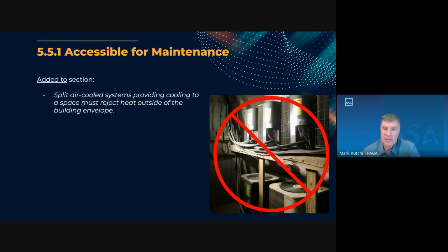I think the issue is that a lot of engineers make the mistake, as shown in the photo here, they just put these condensing units that cannot be ducted. They're not aware of other manufacturers who make ducted type units when they're faced with a situation where they can't locate the unit outdoors. So they use the right piece of equipment, it should be fine, but this is the wrong application. And the obvious reason is, we shouldn't be adding loads to spaces that weren't designed to accommodate them.